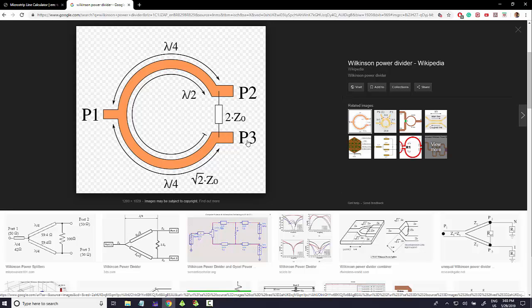And that's the beauty of microwave and RF. I can get this working in a passive and simple structure with all this isolation, with all these matched ports, because I have these 90 degrees transmission lines here and the resistor. That's the difference between high frequency and low frequency. The phase information makes possible this structure with the isolation and the matching at all these 3 ports simultaneously.